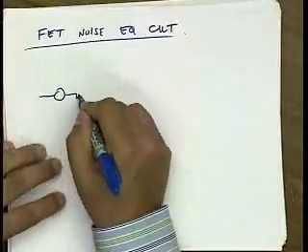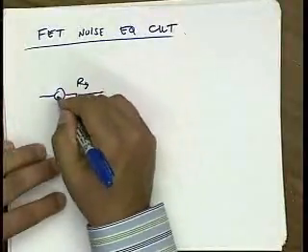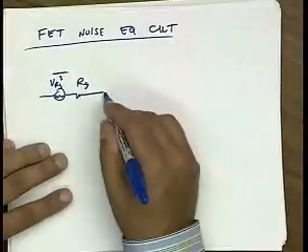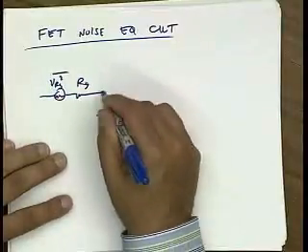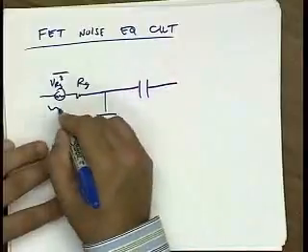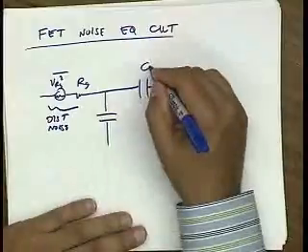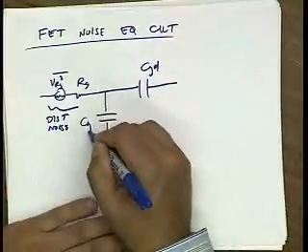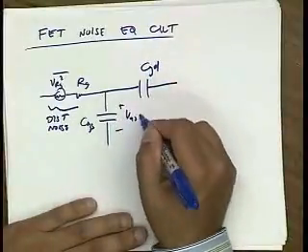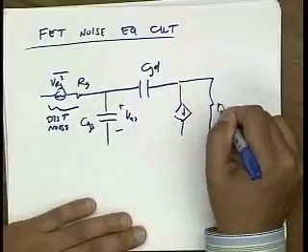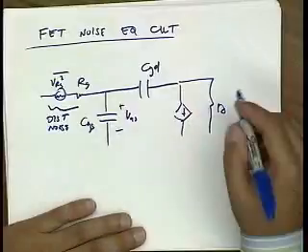And again, we use the small signal model for the same reason. There's some gate noise associated with the gate resistance. Remember, this is a distributed noise source. You have C gate to drain, and you might say, what do you mean by distributed? Well, we'll talk about that later, maybe today.